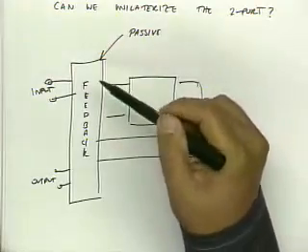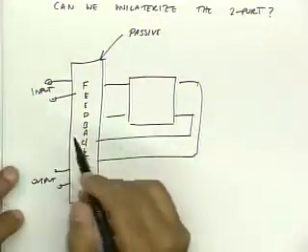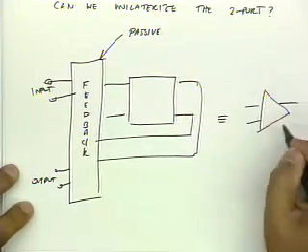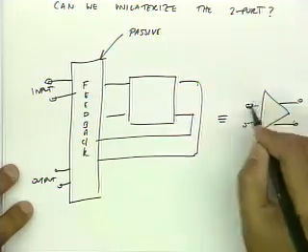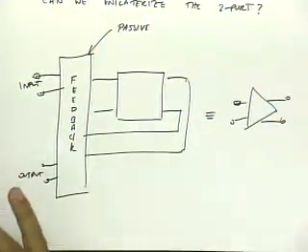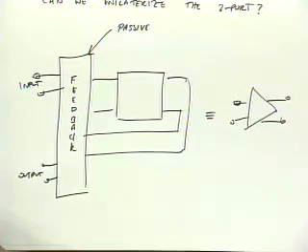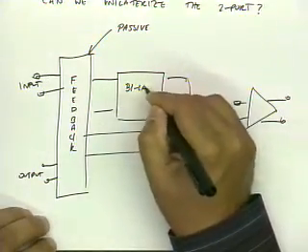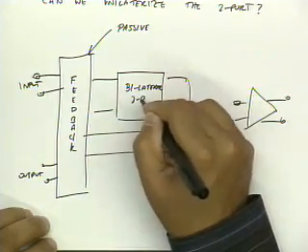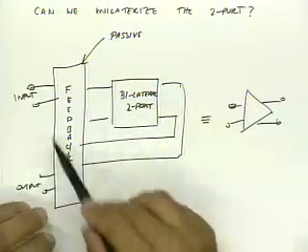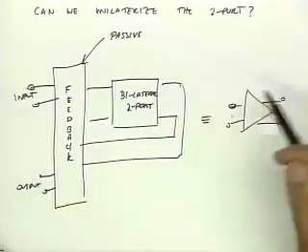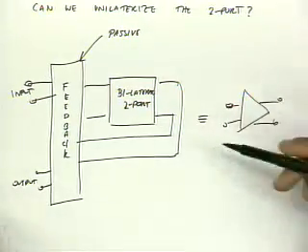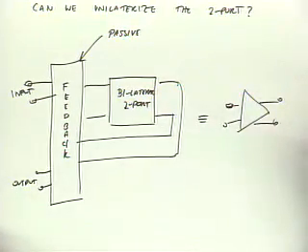And the idea is that I want to create a new 2-port, so this is now equivalent to a new 2-port, which is unilateral. Okay? I haven't cheated, right? I'm not dissipating any more power than I was before. I still have a 2-port. This is my bilateral 2-port, and I'm now going to provide some feedback and make it a unilateral 2-port. And the question is, if I do this, can I actually get more gain out of my device?